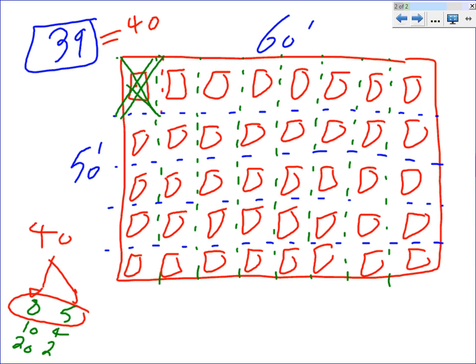If you do it this way, guys, you're going to get 2 things. You're going to get your average foot candle, and you're going to get the best distribution of light in the room. What's the best distribution of light in the room, Spencer? Meaning this area is not going to be too lit compared to this area. The maximum to minimum value of foot candle, you want this to be minimized. You want the brightest spot in your room and the darkest spot in your room to be as close to each other as possible.